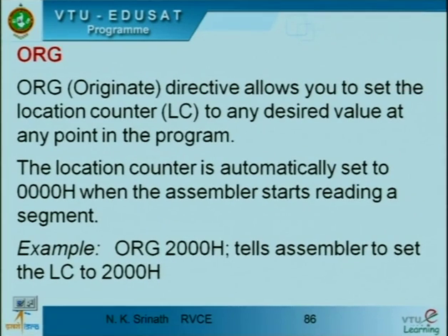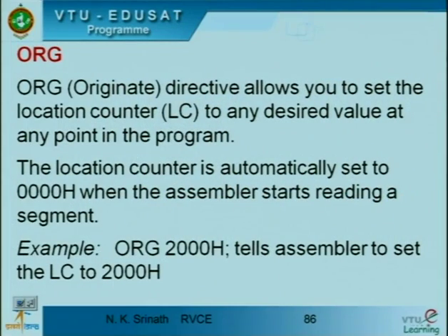There is one more important assembler directive which is very much essential in programming, which we call ORG, originate. This is used so that you explicitly mention to the assembler that the program has to be stored in a particular location in memory. When you are trying to write a program, we are not really aware of which memory location is free. We would ask the assembler to take this initiative and do the operation, but sometimes we know we want it in a particular location where it has to be stored.